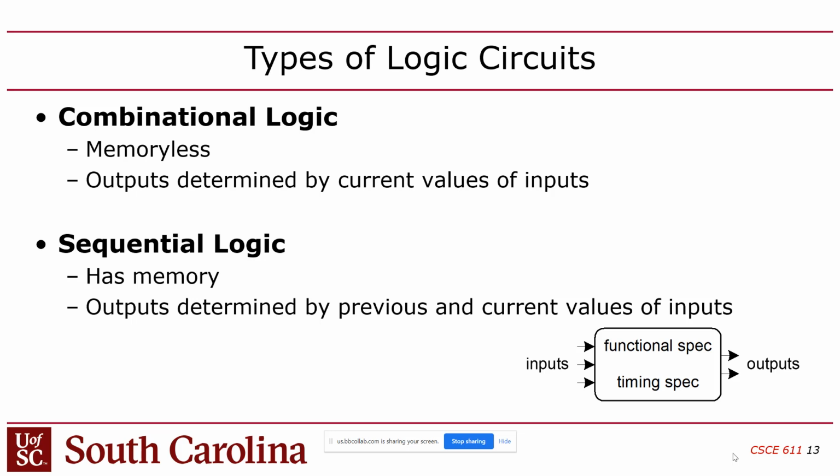Now, is there a different syntax, or a keyword that you have to put into SystemVerilog to define that? No, it just all depends on how you write the SystemVerilog module. It's the same way as earlier, when I mentioned the distinction between structural Verilog and behavioral Verilog. There's no formal way that you specify a module as being structural, which is the schematic, or behavioral, which is the truth table.